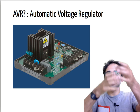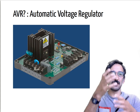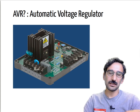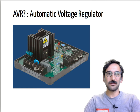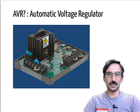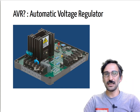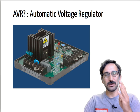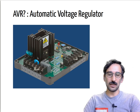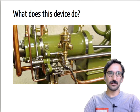So at the end of the day, remember, it is a rotor with some field winding, so it is working as an electromagnet. So you can control how much flux density is generated by controlling the field current, and by doing that you can control the magnitude of EF, and by controlling the magnitude of EF you can control the output voltage. Okay, and there's also another thing that we need to control.